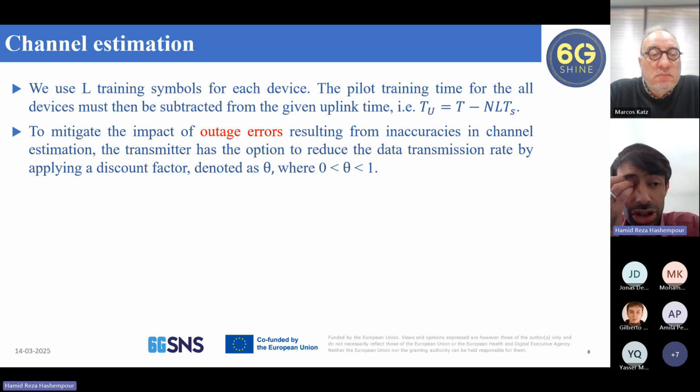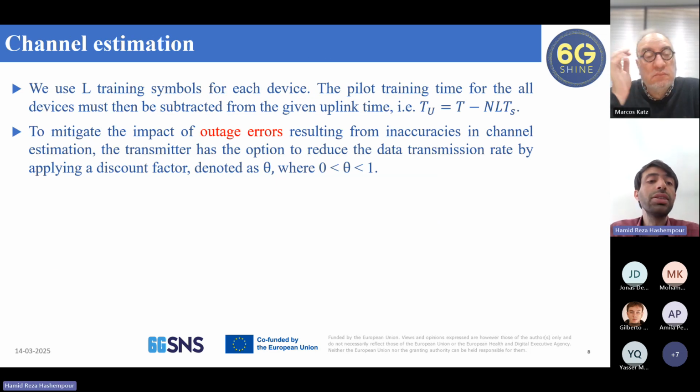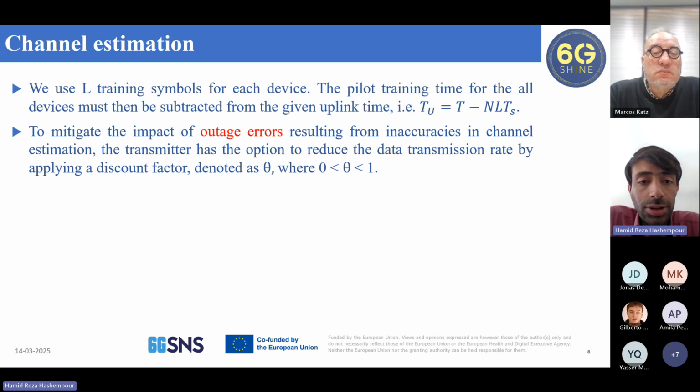Okay, the channel estimation is based on L training symbols that we use as pilot training for estimating the channels. We should emphasize that the uplink time should be reduced by the time needed for estimating the channels. For the special case that we have N devices with L pilots and with the sampling time of TS, we have this time for uplink transmission.